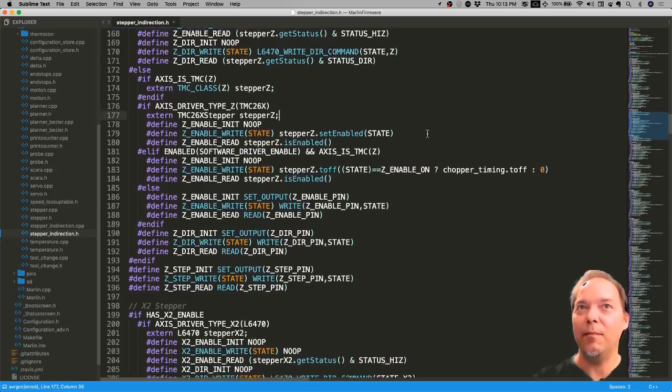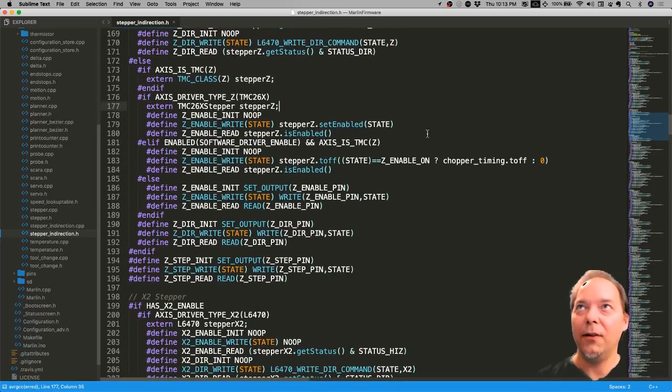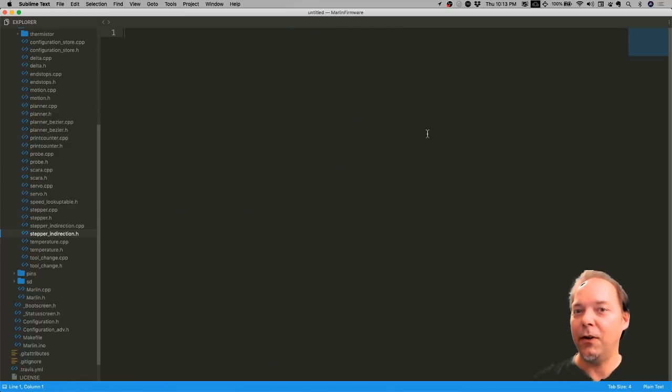This basically makes sure that the steppers behave like they should for the type of machine you have, and for all the add-ons and extras, especially the extruder that you have. It's really cool and worth a look, but it's more the low level: how do I step, how do I set direction, all that sort of stuff is there. And then stepper.cpp, which also contains a service routine which runs as fast as the steps that are stepping.